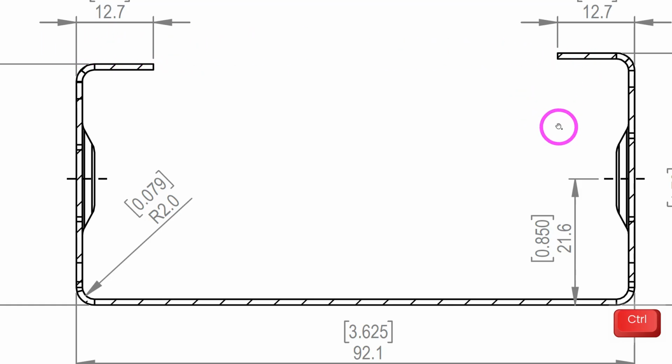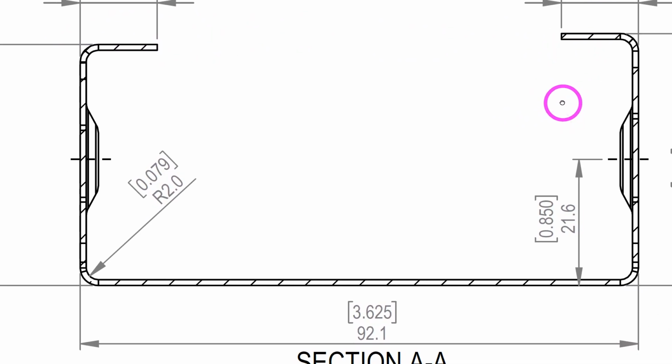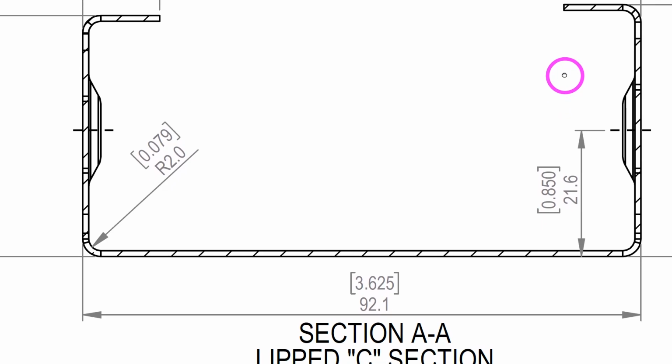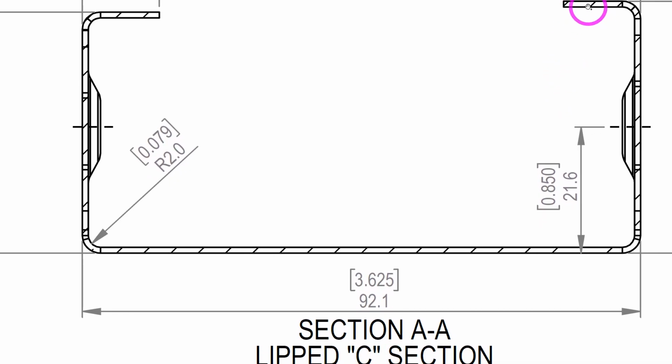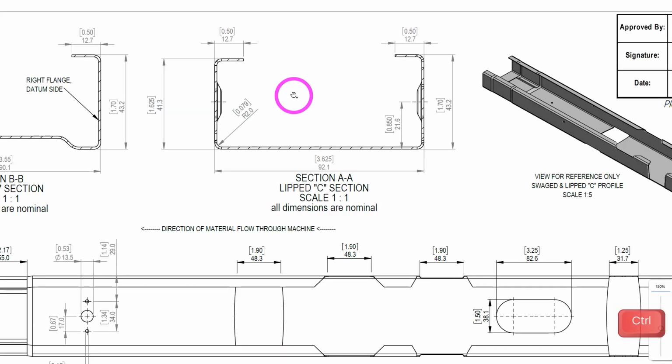If I scooch this all the way up, so this right lip is aligned to the top of my screen, notice this lip over here is lower. Why is that? This is called a boxable profile. It means that if I needed to, I can print out two of these studs and flip one upon the other, and they can actually squeeze together to create a box section.